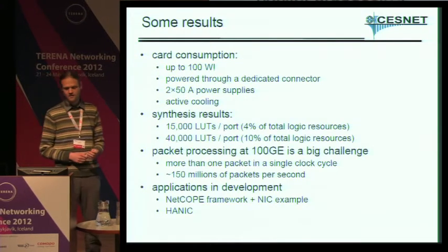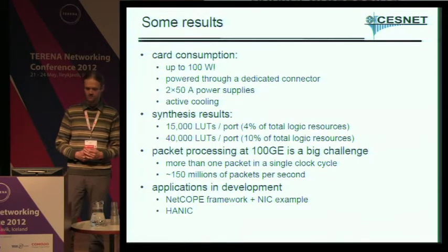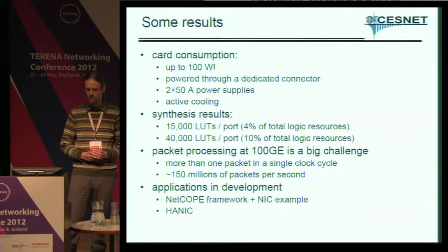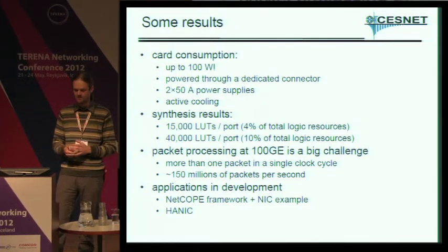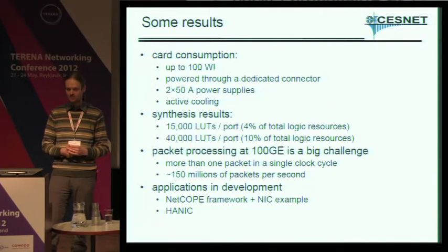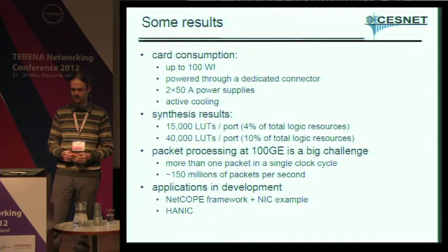Some preliminary results. Card consumption will be up to 100 watts. Therefore, we will have to power it through a dedicated connector. And one of the reasons why the card is so big, it's full-size PCI, is that we need to have two 50 amp power supplies to get enough current for the FPGA and the other components. Of course, we will need active cooling.